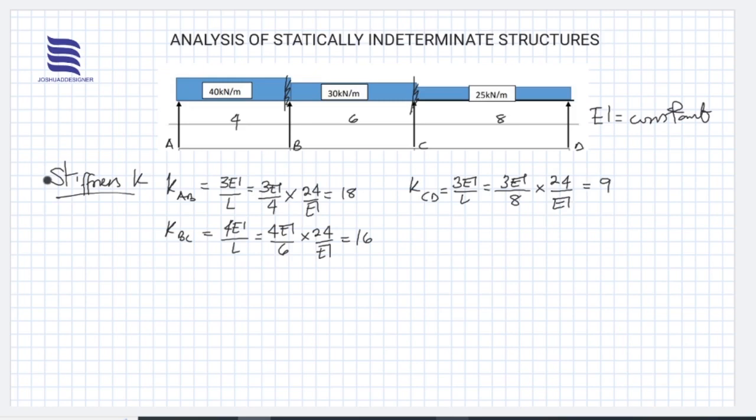Right, so these are the stiffness values, and yours might be different basically because of the uniqueness of your beam arrangement. So you should not just find this and stick to it. You have to understand what's peculiar to the beam you are designing, then apply appropriately the stiffness factors. Right now, we have the distribution factors.